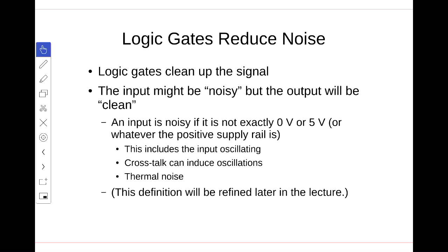It's actually the waves in between the traces that carry all the signal, etc. And you get crosstalk, meaning you send a signal down this pair of wires, this other pair of wires is going to get interference from it, and you'll get these oscillations there. When you've got digital circuitry switching very quickly, you get huge spikes in the power rails, and these power rails are connected to all sorts of other chips there, and so you get noise everywhere.